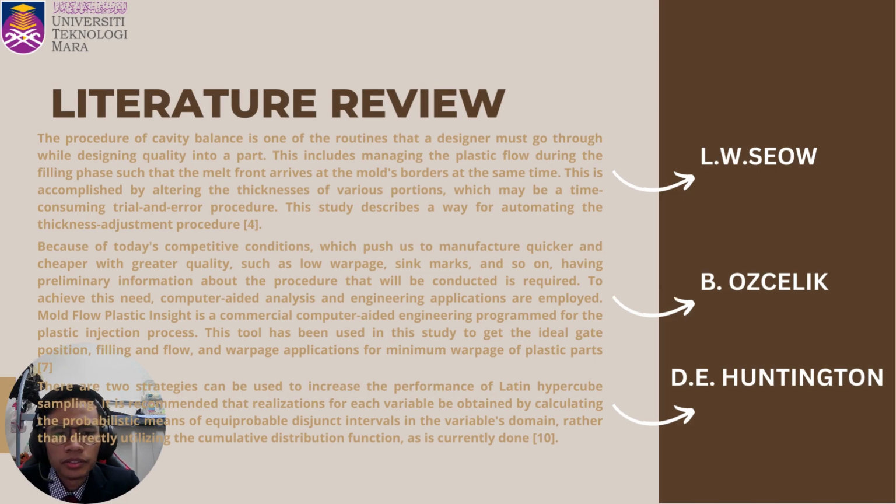Next is literature review. It is stated in the research that the mold and the component design of plastic parts for injection molding is a complex process with factors ranging from cost and manufacturing speed to structural, ergonomic, and aesthetic criteria. The procedure of cavity balance is one of the routines that a designer must go through while designing quality into a part. This includes managing the plastic flow during the filling phase such that the melt front arrives at the most distant border at the same time.